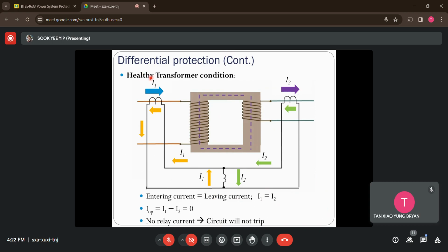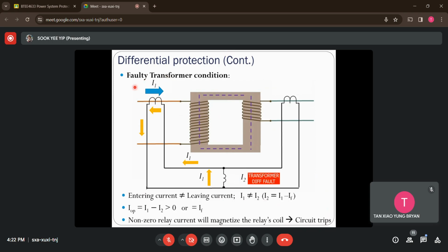This is the healthy case. So what happens? I have the transformer right now, so we might have the winding at the secondary side short circuit to ground like this case here. Under these situations, because of this short circuit path with low resistance, the current will not flow up. Instead, it will change its direction and flow through this short circuit path to the ground.